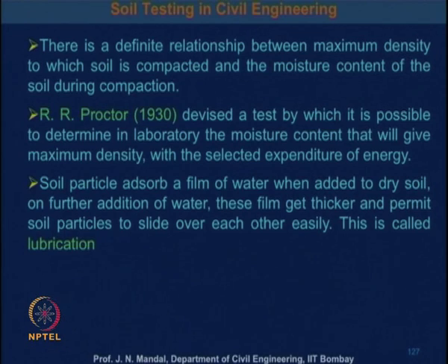Soil particles absorb a film of water when added to dry soil. On further addition of water, this film gets thicker and permits soil particles to slide over each other easily, and this is called lubrication.